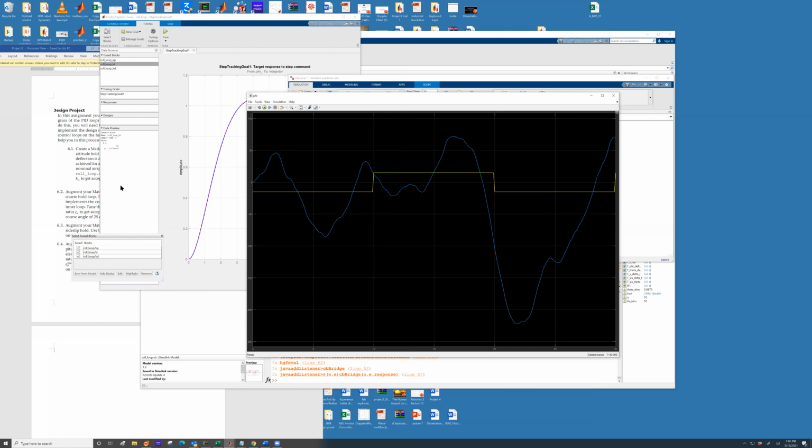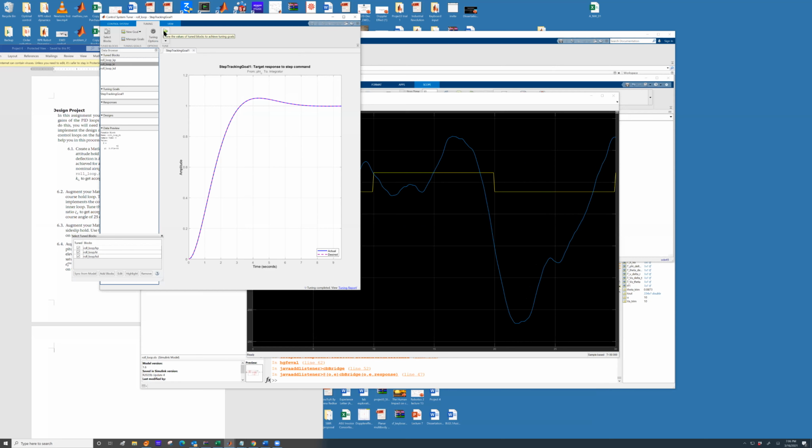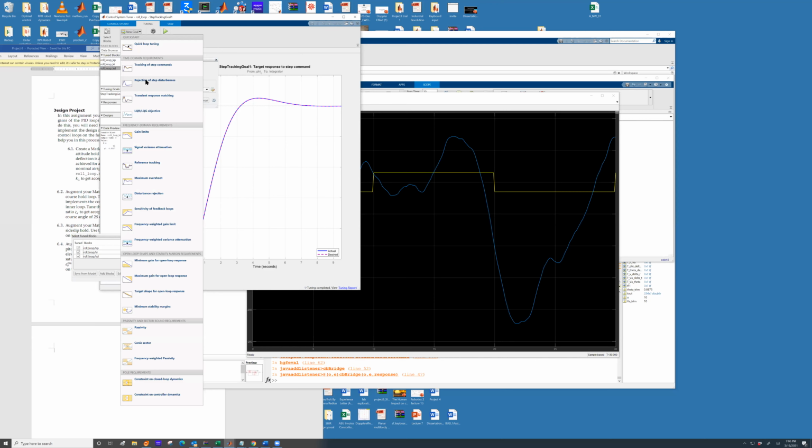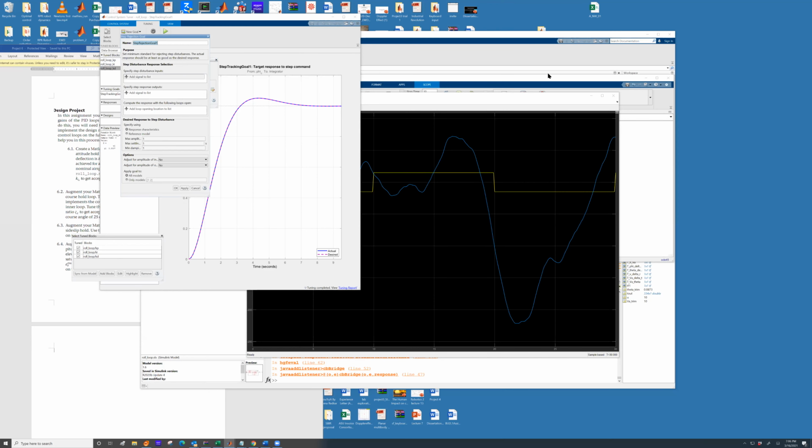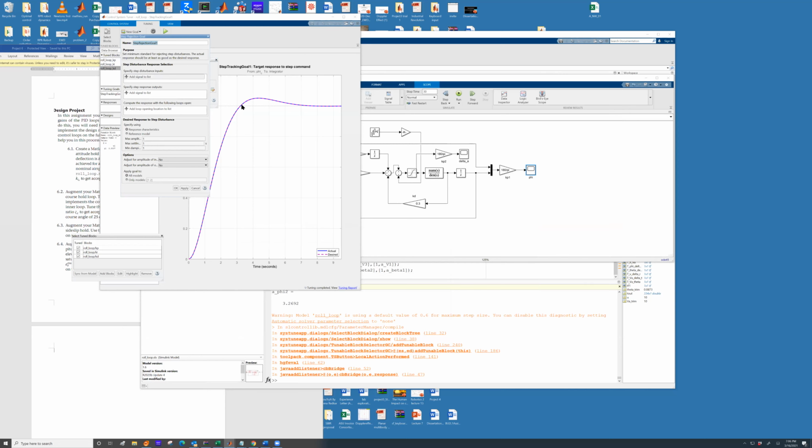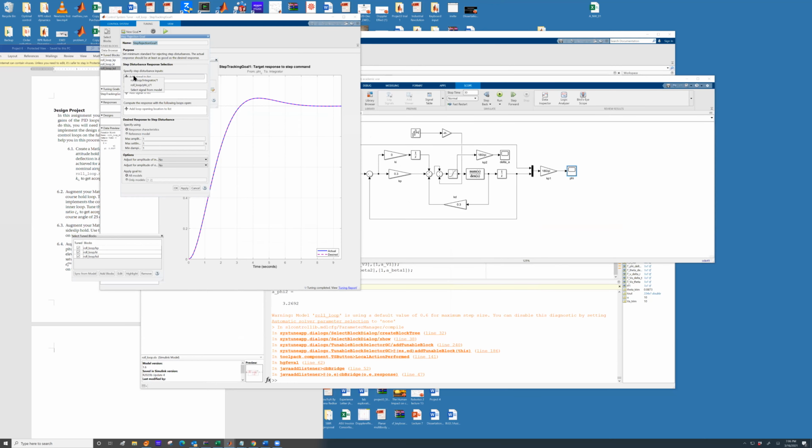At this point, we can actually try to tune it, but you will notice your gains. Now, if you tune it, let's see what is KP. KP has not changed. KI has not changed. KD has not changed. But what I will do now is change my goals to rejection of step input disturbances. And again, I can do the same exercise.